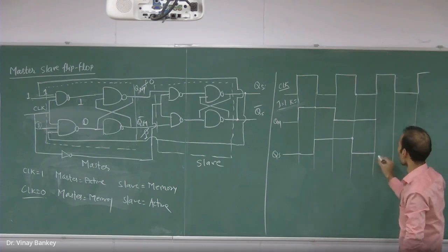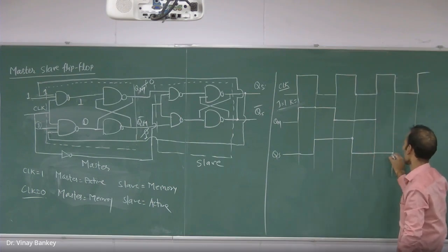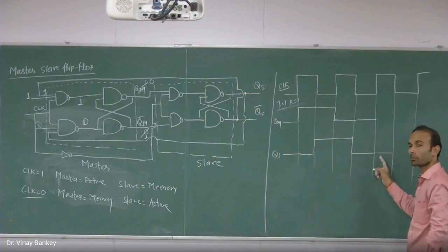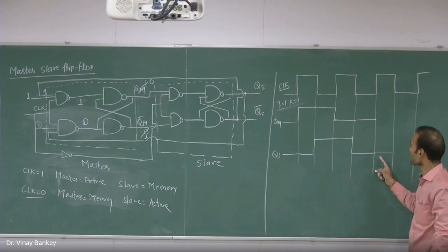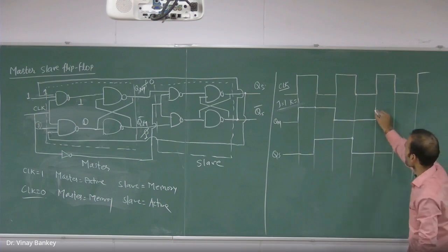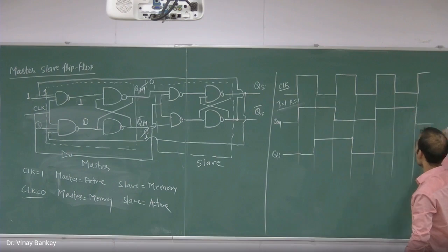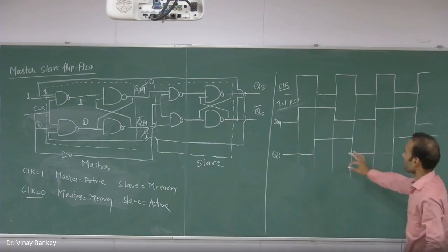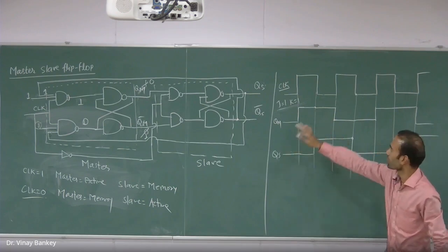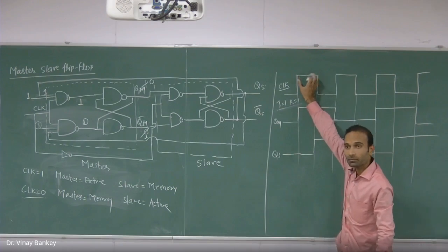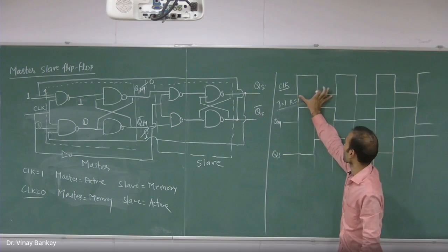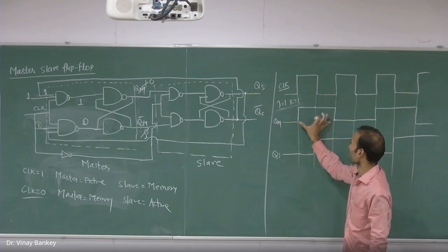And for the high clock pulse, this QS will be in memory state. So whatever the previous condition, whatever the previous output, that will continue. Okay, now accordingly, this will again change. So is it easy or tough? Whatever it is, see, now we don't have toggle or racing condition in a high period. For a particular time period of the clock pulse, we have a stable state here.